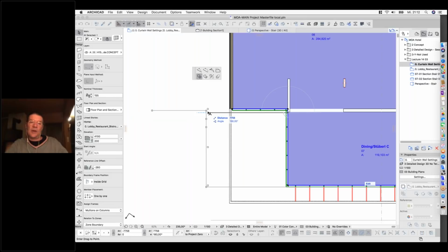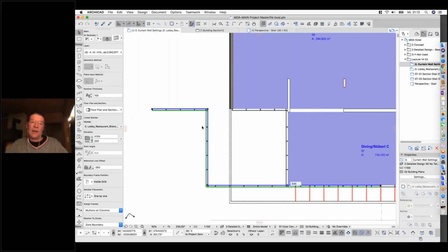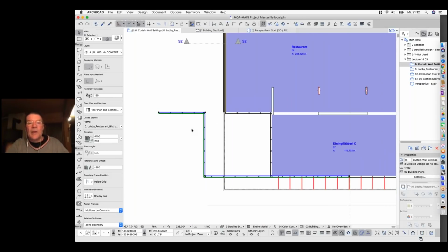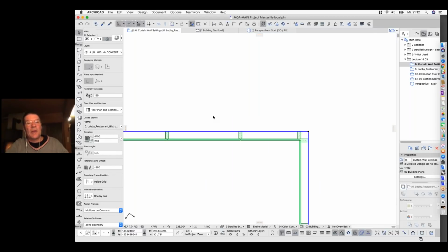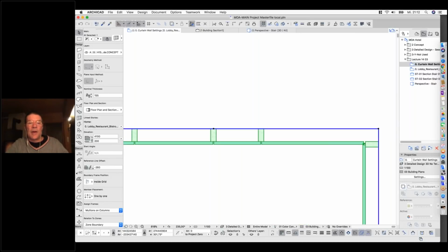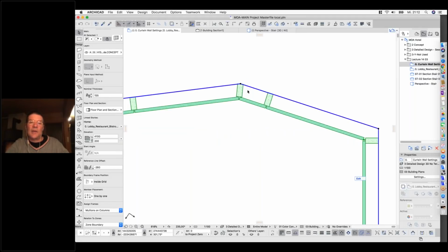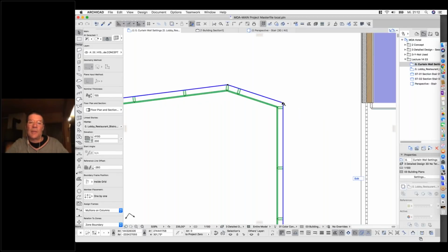Whenever you are changing an element like that, you're doing it by setting nodes. And immediately, if you're setting a node, ArchiCAD will react. And it's setting, of course, a boundary frame on this node. And it's getting even worse if you are, let me say, moving the node. And you can see ArchiCAD does best guess, and it moves the boundary frame here on the middle.